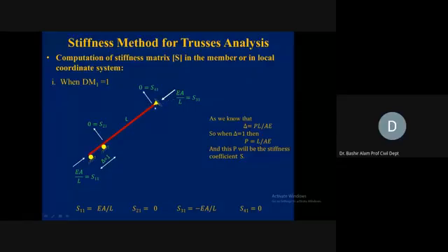So this end is locked, and here we are only providing displacement in the direction of the x-axis. So this roller guide is provided. Why are the arrows towards the member? The reason is that it is shortening, and shortening is always due to compression. This is why this member is shown with compression. These two arrows are looking at each other.